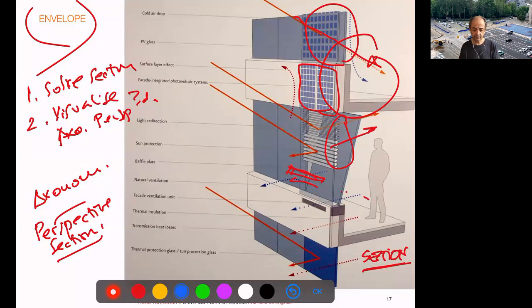The natural ventilation: it's amazing that still many places are not allowed to open the windows. And you remember we commented that in Korea, traditionally you can open the whole room to the exterior, but we keep building those curtain walls with tiny, tiny windows, which are really suffocating in summer. So this kind of opening is something we could consider seriously in the climates, or the automatic aeration, which we see in cooler climates. And again, this could be useful in a Korean winter, in which you still need fresh air, but you cannot have all that heat loss.